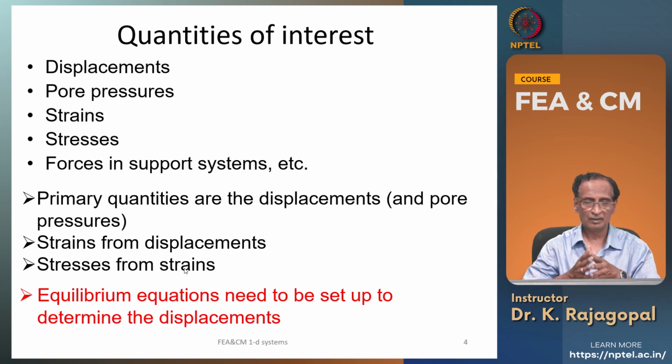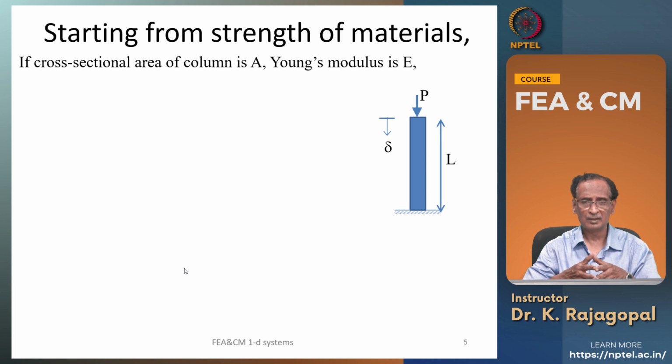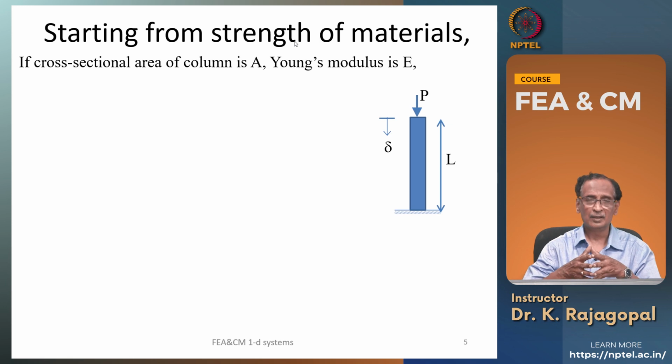And initially we will discuss only the problems with only displacements, that is the elasticity problems, and later we will introduce water and discuss the poroelastic problems. Okay. So, let us start from the most fundamental, strength of materials, because all of us are familiar with this famous equation delta is equal to PL by AE. Okay, that is the equation that we study first in any of the strength of materials courses.